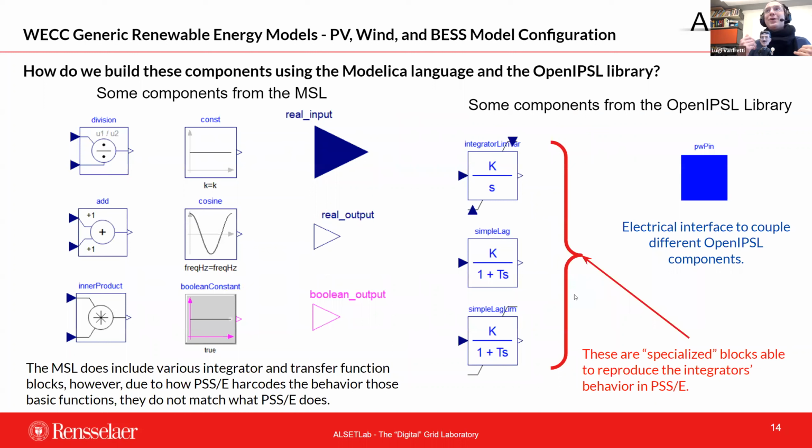So how do we build those? We use the Modelica standard library for everything we can. And if something behaves differently in PSSE, we have to re-implement it from scratch. We actually have to make a tiny little model in PSSE and try to figure out what the integrators were doing for that specific model. That's a lot of clean room engineering that we have to do, but we can implement this using the specialized blocks in our library.